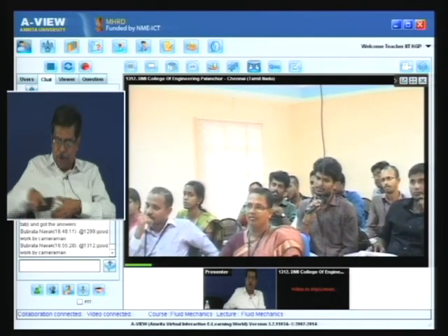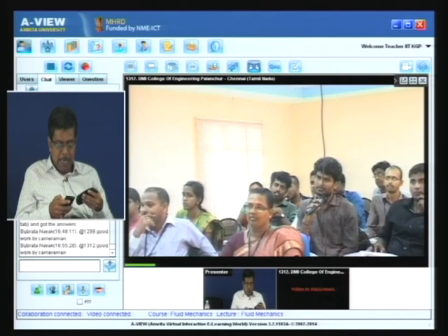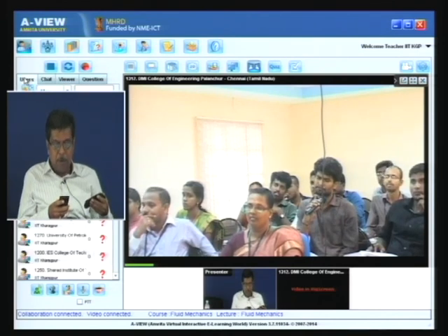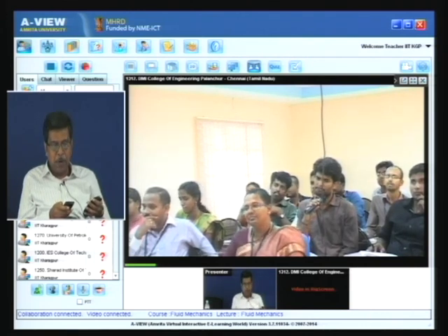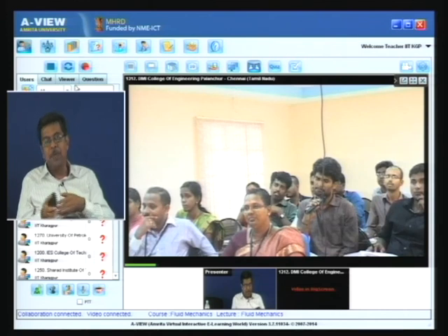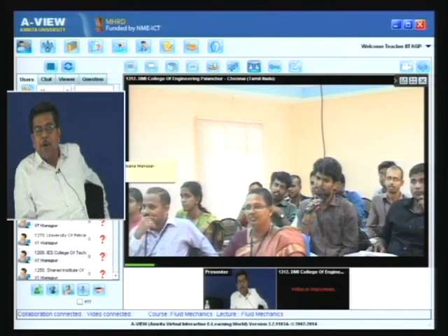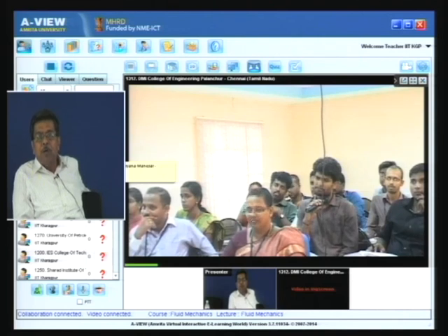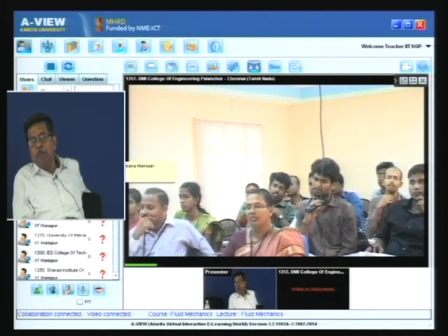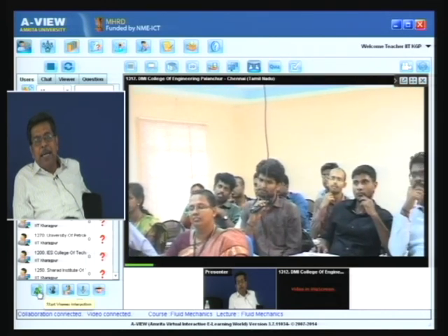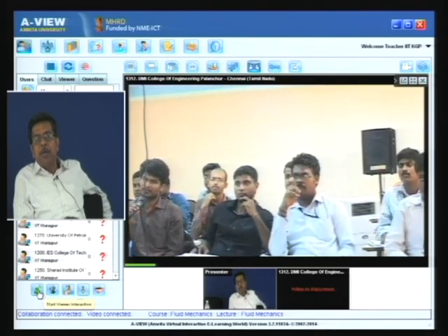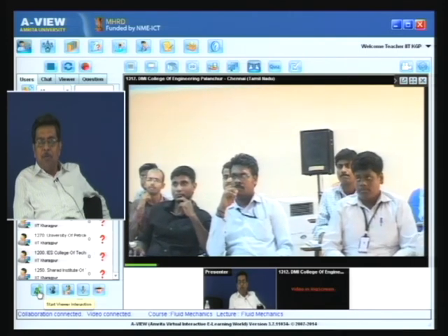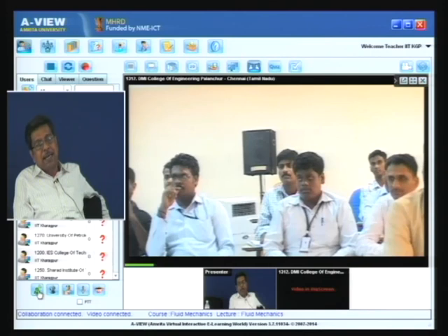Therefore the mass flow rate of fuel is neglected, and in most cases we can consider it a steady flow: the amount of air which is coming in through the intake is going out through the propelling nozzles. So you have to take care of inflow and outflow momentum, and accordingly you have to analyze through the Reynolds transport theorem. So similar to nozzle, similar to rocket you can do, but not exactly in the same way.